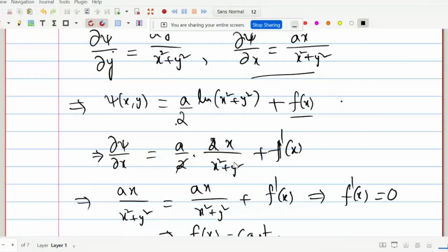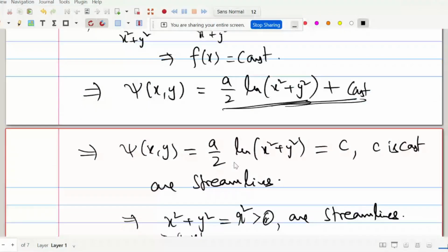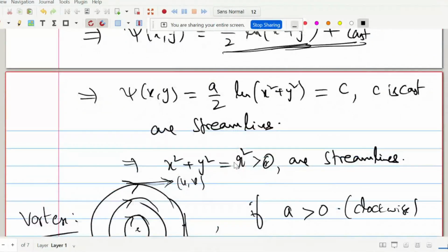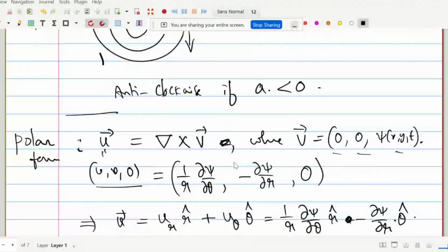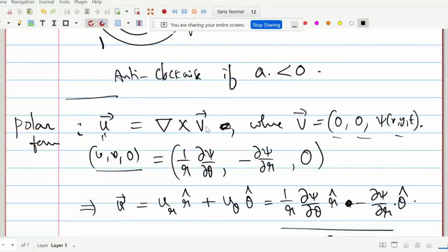That's how you define this stream function. So for 2-dimensional flows, you are able to get a stream function as a scalar function. If it is 3-dimensional, you really don't know how to construct it. V bar itself acts like a potential, where only the third component is a scalar function and the others are 0. If you consider a 3-dimensional flow, you cannot choose this way, since it may have other components.